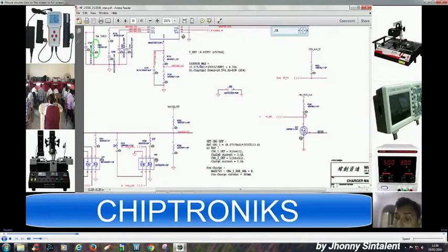This is an N channel MOSFET, so if this AC OK is coming, then this MOSFET would get turned on and the ground would shift here. So this AC_EN is active at 0 volt, and when this MOSFET becomes active, the current will move here and the voltage would become 0.